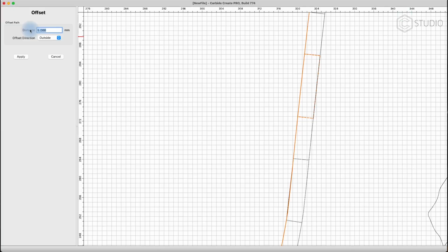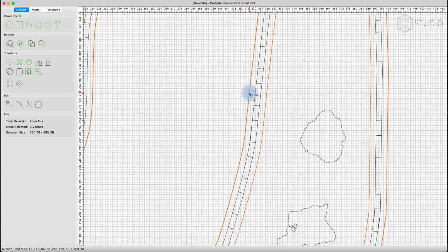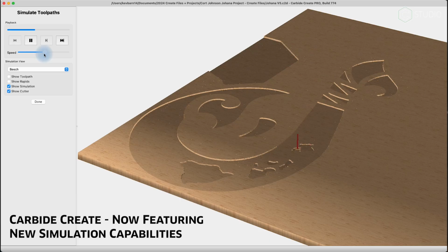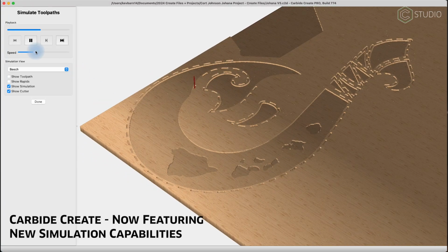Having the visual representation in front of you while you design goes a long way to helping you make better design choices the first time. I ended up selecting an offset value of 3.5 millimeters from each side, combined with the existing 5.5 millimeter hash mark pockets. I thought that outer border would look good, be strong enough to survive transport, and provide some mounting options. Experience and experimentation informed this decision-making process. Additionally, the use of simulation will give you insight into your part before you make it.